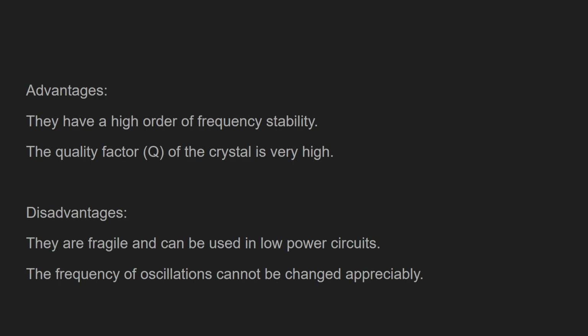Advantage: the quality factor of a crystal is very high. The frequency is really accurate compared to an LC circuit, and it can have very high stability. Okay, but they are very fragile. It is a piece of stone, right? A very thin piece of stone, and it cannot withstand a lot of power, so it can be used only in low power circuits. You won't see a quartz oscillator in very huge or powerful circuits, or circuits which take a lot of energy.